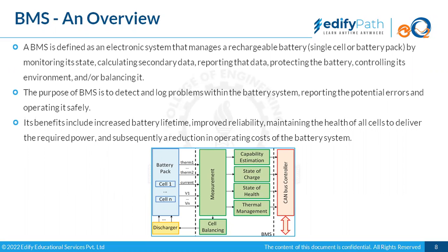In case the BMS feels that the conditions are not safe for the battery to operate, it would disconnect. Even if any safety features of the controller are bypassed, or if both are programmed at different levels, it could be that we have set the higher and lower voltage limits for accepting charge on the higher side in the controller, but on the lower side in the BMS.